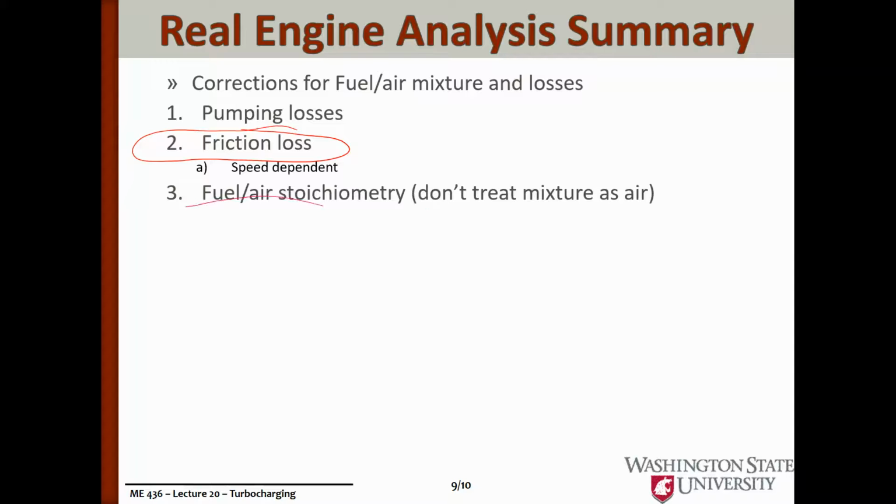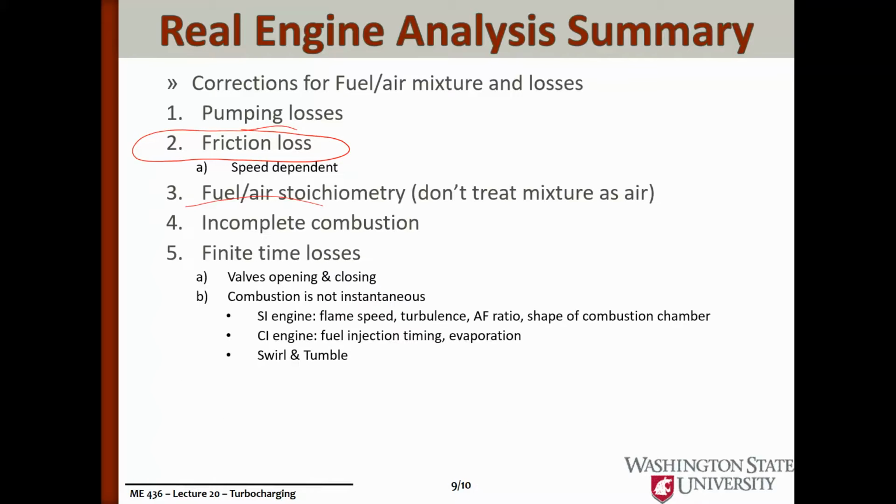We spent a while going through the stoichiometry, the fuel-air combustion. We worked on incomplete combustion when we talked about equilibrium. We talked about the things that are occurring in finite time. So we removed a lot of those timing assumptions. So we talked about the timing of when valves open and close. We worked with the time that combustion takes to occur, related that to flame speed in an SI engine. We did a little problem with homogeneous ignition time for a CI engine.